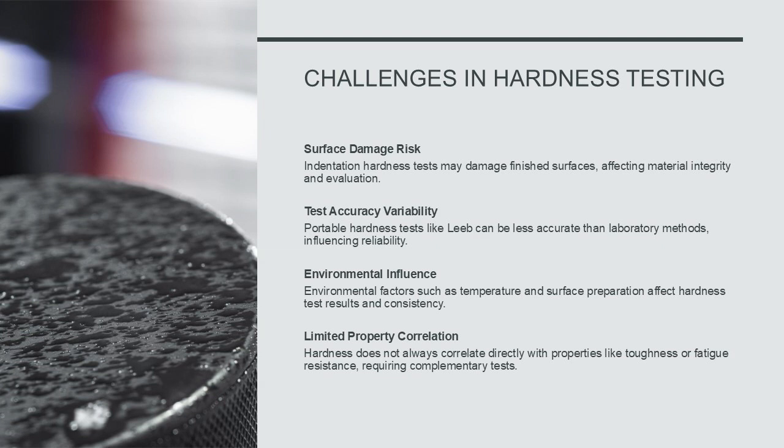Environmental factors, such as temperature and surface preparation, can affect results. Additionally, hardness does not always correlate directly with other mechanical properties like toughness or fatigue resistance. Engineers must consider these factors when interpreting hardness data and complement it with other tests for a comprehensive material evaluation.